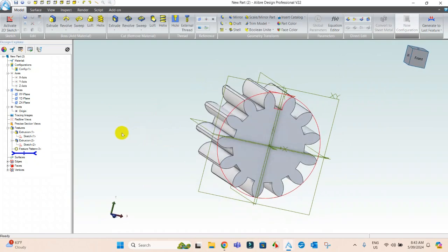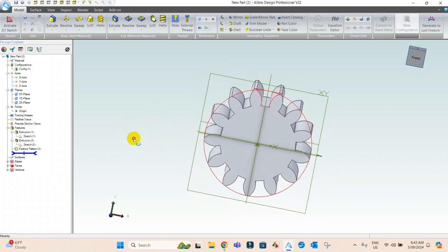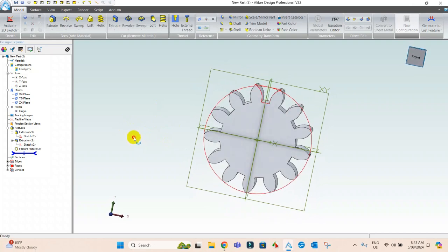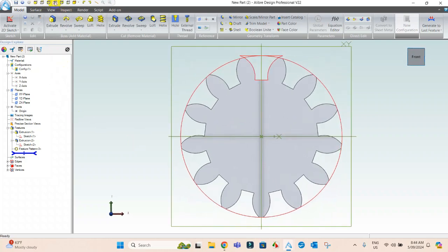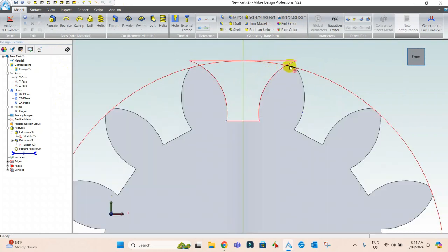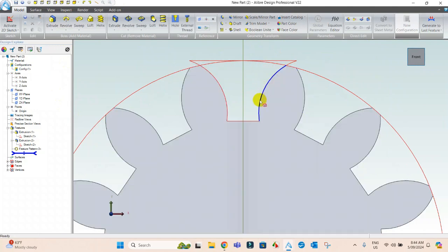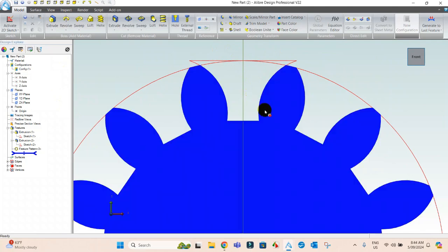All right, so there's my tooth. Now there's a few issues with this particular model, and CAD models. You can do anything in CAD, but not necessarily do it in the real world. Let's look at this straight on. Going a bit tighter, you'll see here my tooth. Of course, the radius is quite pronounced now. Your cutter that came and cut this would undercut in that area there. Well, you can't do that. It would make that straight.